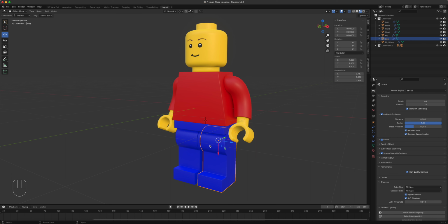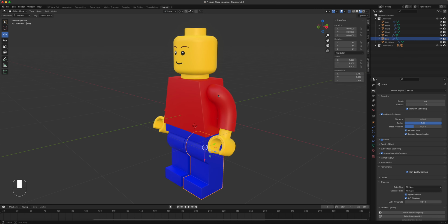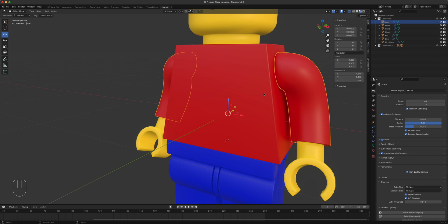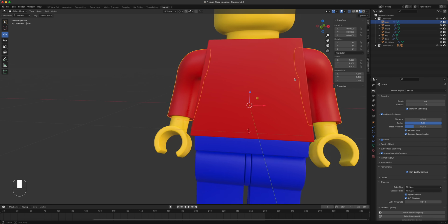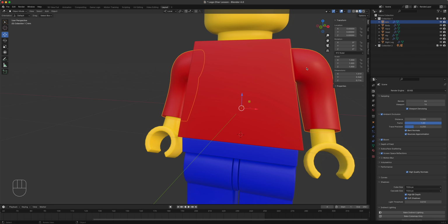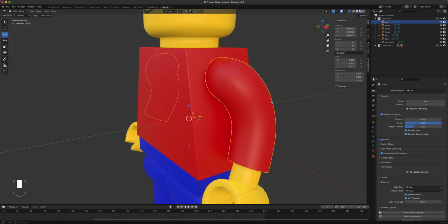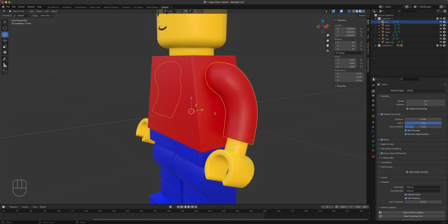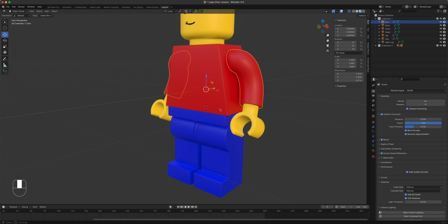We're going to go to global right here, but we're going to animate this in local, because there's some angles right here. If you rotate this, even when its pivot point is on the X, there's an angle right here. It will not rotate properly. It will go through the mesh. So we're going to be animating this in the local coordinate system, meaning it follows the orientation of the local axis, how we set it up.